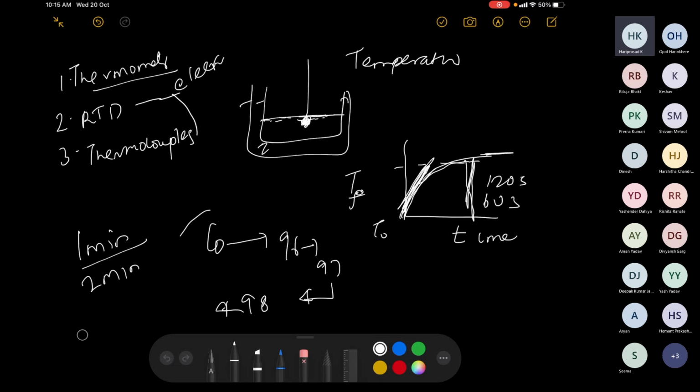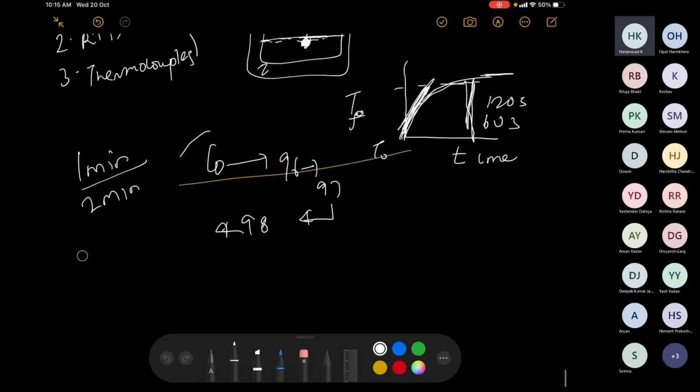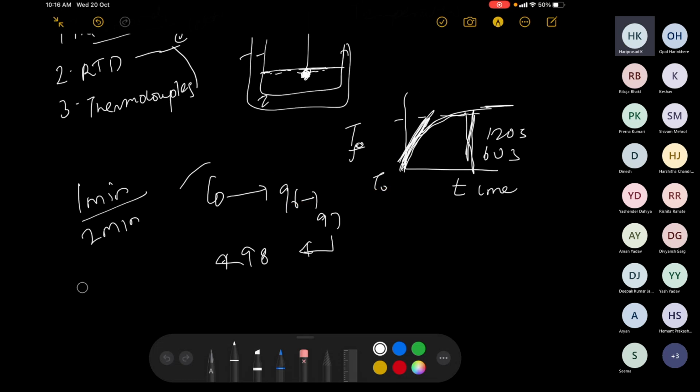Eventually this is what is happening. So what you really see is that there is a dynamics involved. When you try to measure the temperature, it sometimes takes time to reach the required steady state. So you would most likely see this as your characteristic. This is fundamentally modeled as a first order system. So you have K by tau sensor s plus 1, because eventually it will reach the steady state, but it takes some time. So this is a classical first order system.